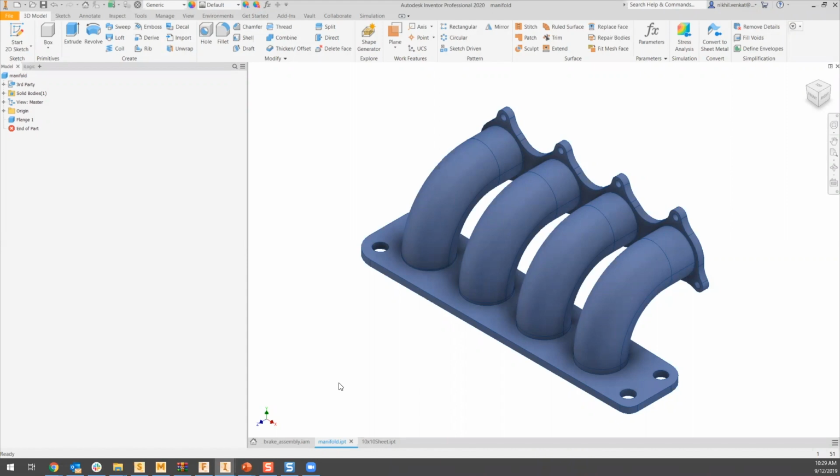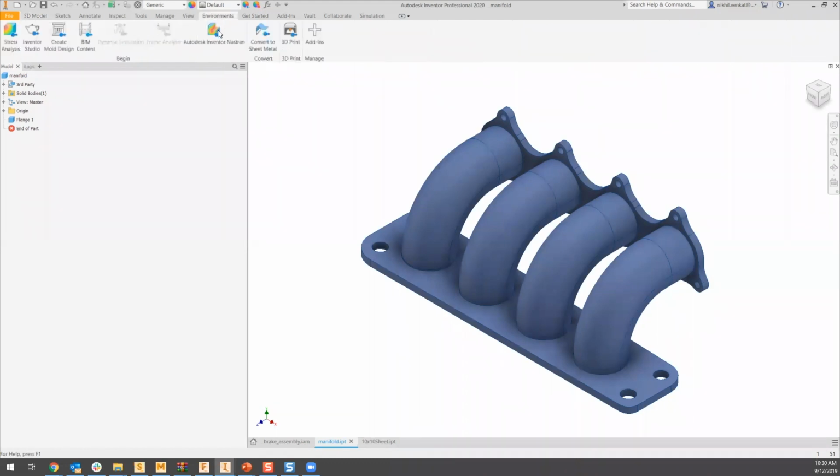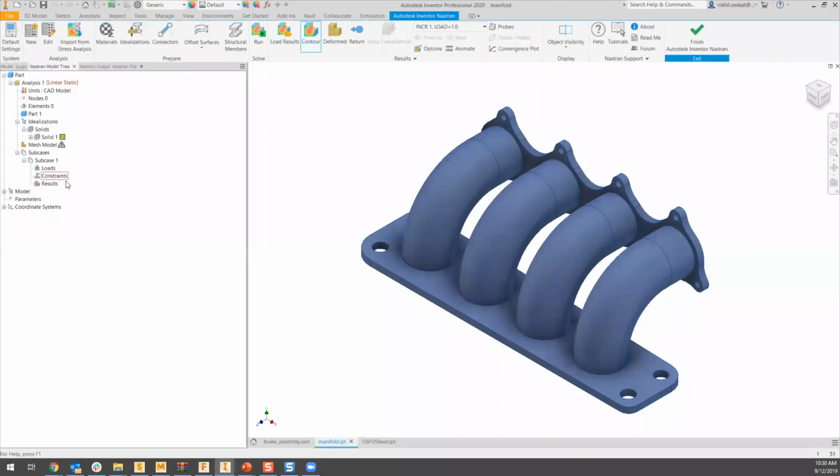We defined that variation. We defined the XY plot there. Now in this next one, we're actually going to allow the software to do that. Some of you may have seen this model before. This is one of your tutorial files, by the way. So you will be able to find this in the tutorials, in the Nastran tutorials.